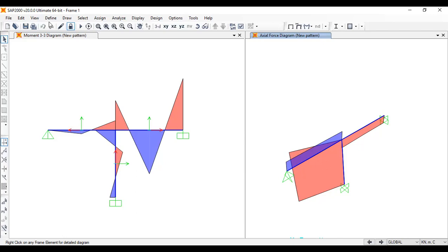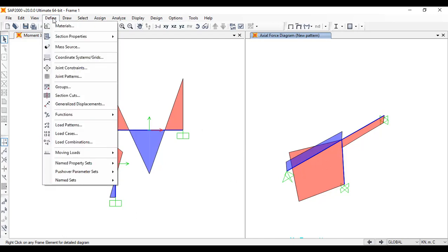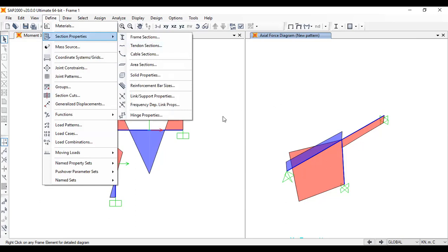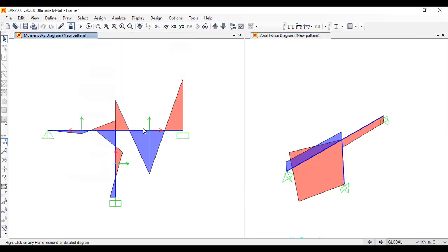You can just run this application without even assigning the materials. Then you don't know what material it is, but you can still calculate the bending moment. Why? Bending moment doesn't depend on the E value. Remember? But when you calculate the deflections, that will matter. Those are the basic concepts you have to know. Modeling is easy. I'm repeating, modeling is easy, but interpretation and linking your concepts is the hardest thing. So I leave you to try that problem.